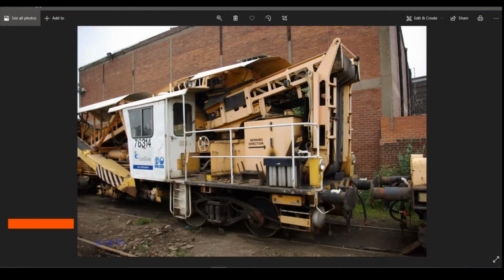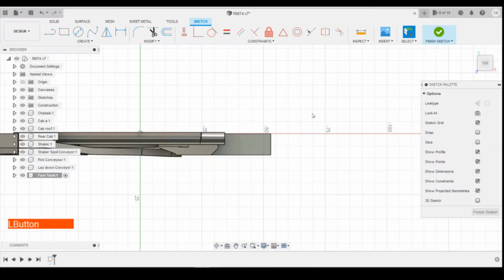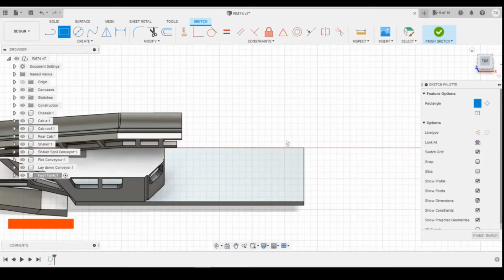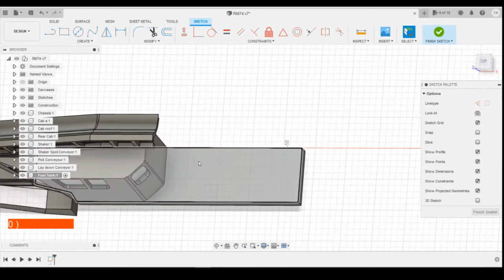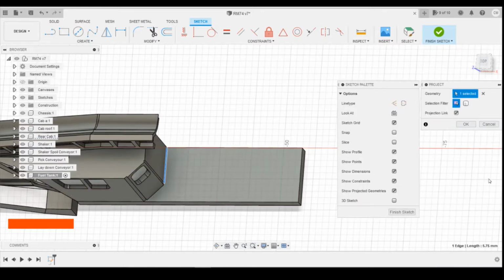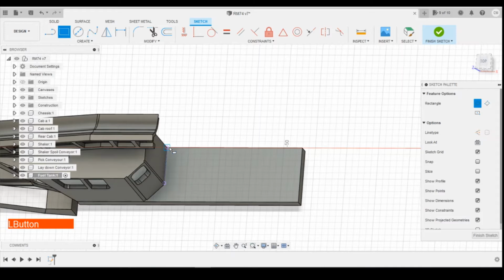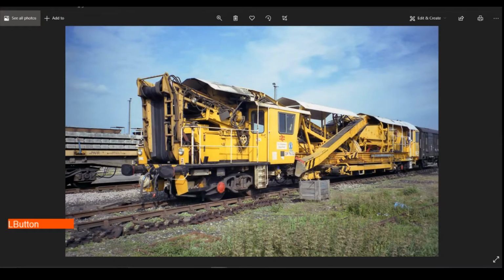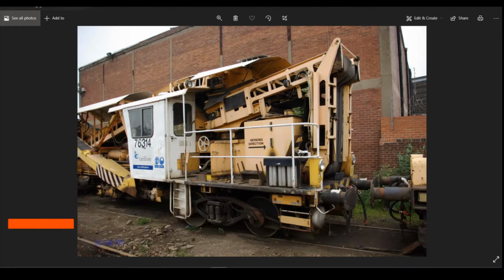So if we look, we've got the cabinet start where the door ends, and then this one steps out slightly. So what we're going to look for is drawing a rectangle initially, and to start with, we're going to project that line on there, and we're going to do a rectangle starting in the corner. I'm going to drag it out to match it. I'm not really sure how far out we're going to come, but I'm probably thinking that's a good halfway along this section here.